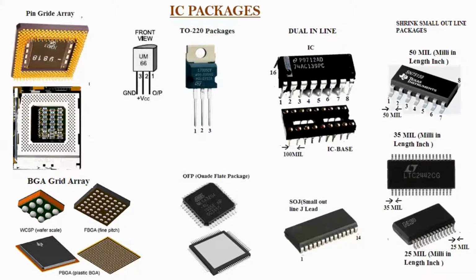Okay. So likewise, if it is more than 3, it can be an 8-pin IC like 555 or an operational amplifier, which will have 8 pins. Dual in line, it can be 14 pins, it can be 18 pins or more than that, right? So we have different packages and different sizes of IC decided according to their shape, size, and pins. For example, you can see on the slide a pin grid array, right?